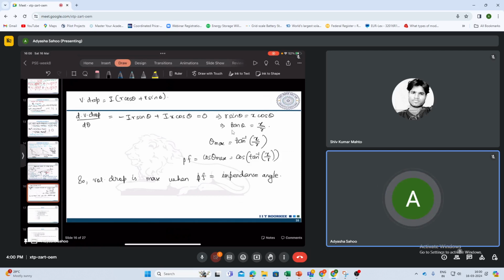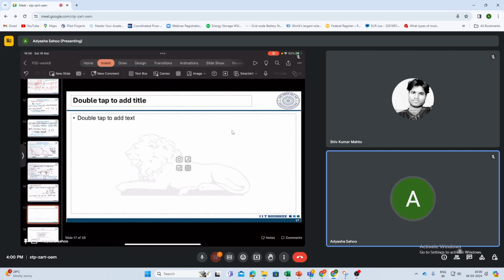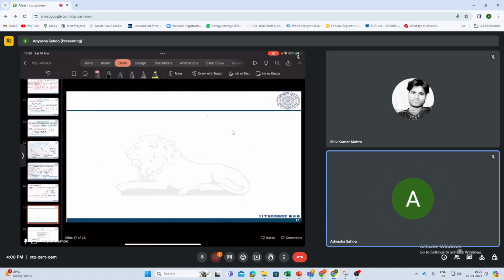And now, lastly, we'll see for a radial system how to calculate this voltage drop. So let's say we have a load drawing IC, IB, and IA. These are VA, VB, and VC. Let the branch currents be I1, I2, and I3. So what will be I1? I1 will be IA plus IB plus IC.